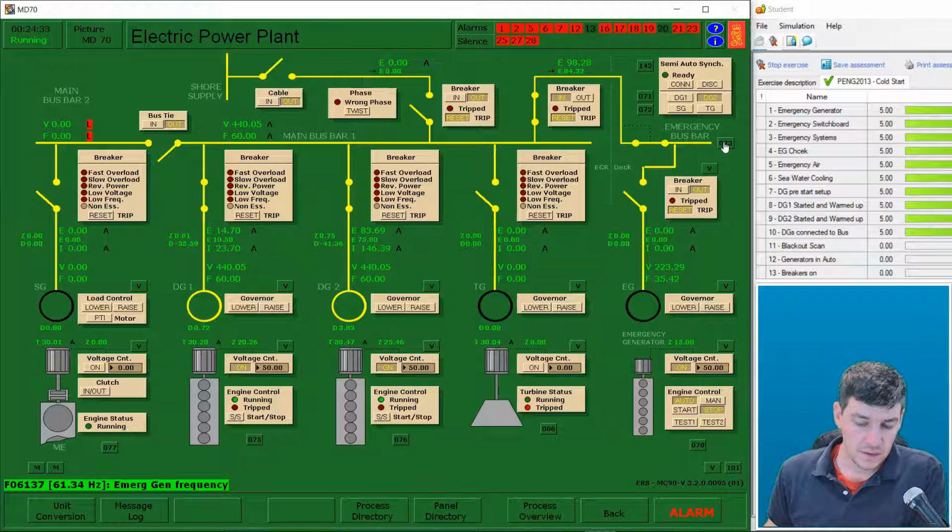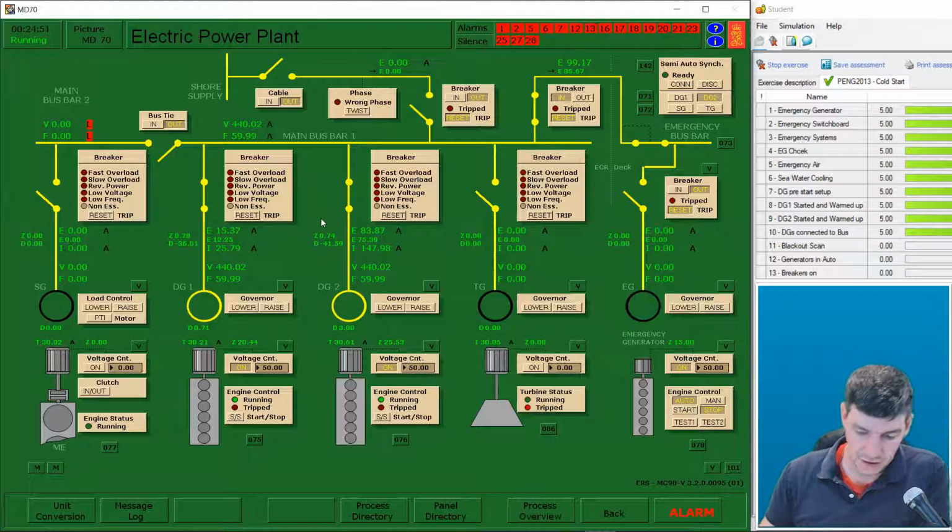Okay, when I did that switch over, I didn't synchronize these generators, so there wasn't a synchronization in and out for the emergency system. What happened is I disconnected my power to both, and then I connected the generator I wanted. And what that meant is that I had a moment where I had no power.